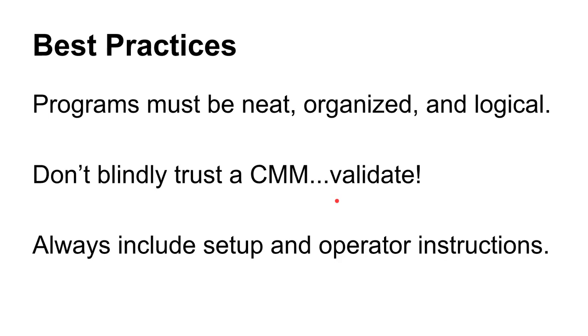It might very well say yes. Okay, but that's going to depend on the 5 points where you chose to probe that thing. And if you're trying to evaluate flatness with 5 points, then that's probably not the best way. So be careful. The CMM will give you the exact answer that you ask.